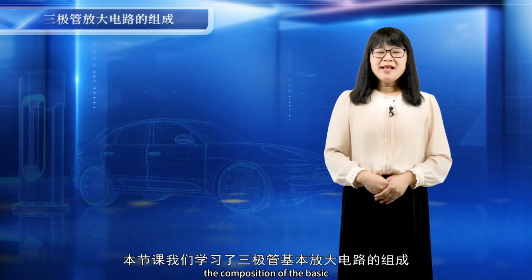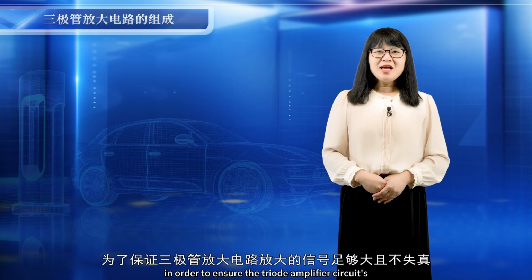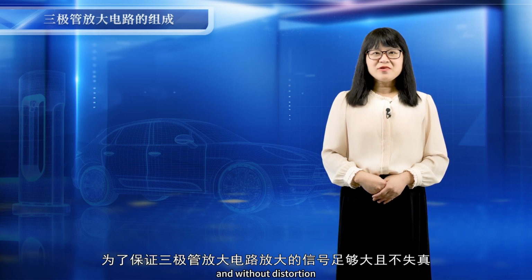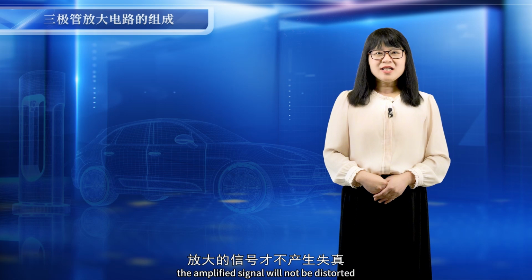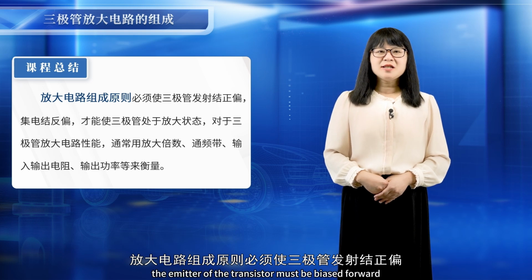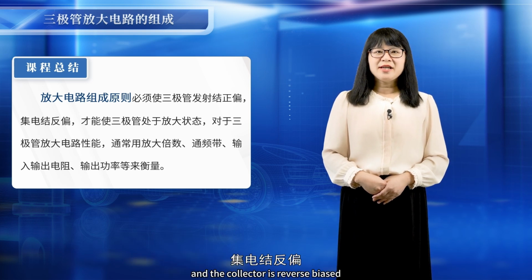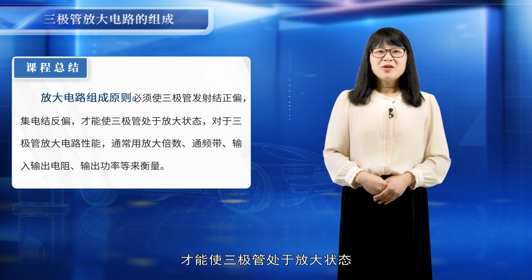In this class, we have learned the composition of the basic amplifying circuit of the triode. In order to ensure the triode amplifier circuit's amplified signal is large enough and without distortion, only by making the triode in the amplifier circuit operate in the amplification region will the amplified signal not be distorted. The principle of the amplifier circuit is that the emitter junction of the transistor must be forward biased, and the collector junction reverse biased. Can the triode then be in the amplification state?